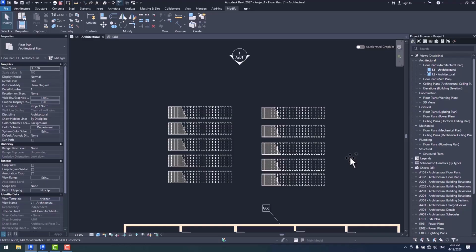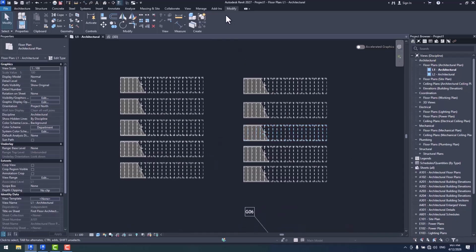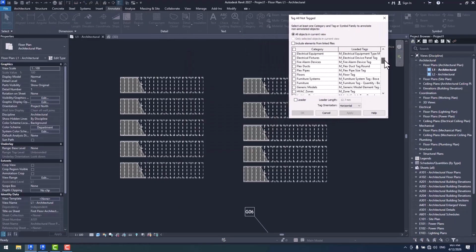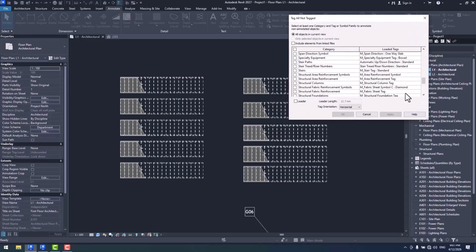So to sum up, guys, this is going to be a golden feature that we will be able to use within our work without any difficulties. Take a look at this. Entering the Tag All tab, here we can find both stairs and stair path. For stair path, you would be able to specify a type.